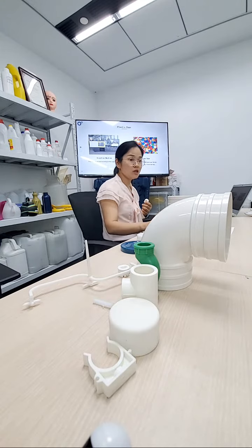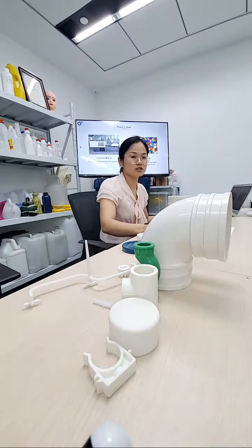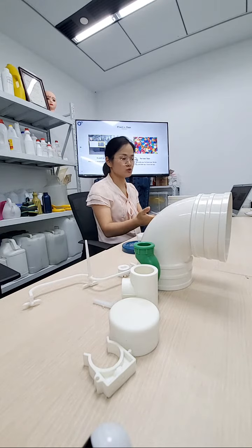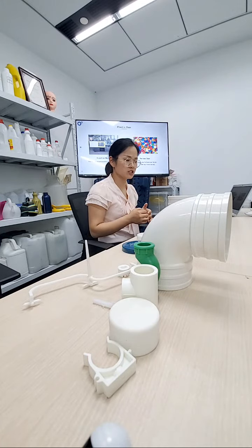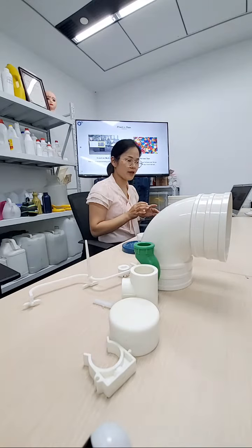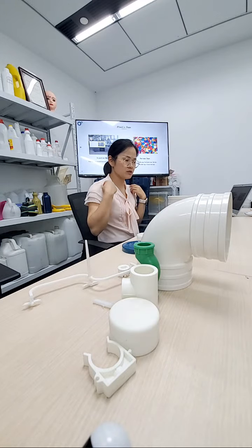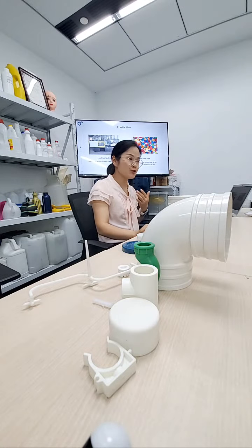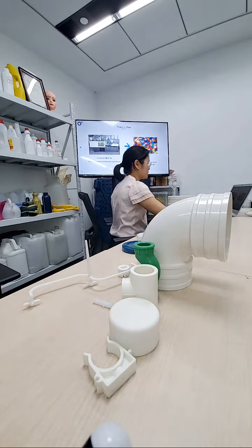For example, usually for producing 5 liters jerry can anti-theft cappers, we usually use a 95-ton injection machine with 4 cavities. The production capacity is around 580 PCS per hour, because usually for producing the 5 liters bottles, the production capacity is about 500. So this model injection machine can meet the requirement of the bottles production line. Let me show you some videos to learn more about our machines.